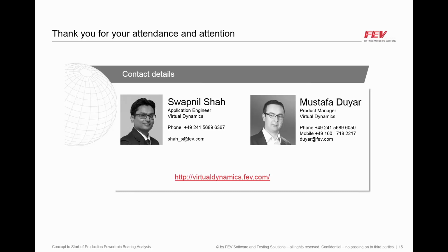So I'm guessing this question is for the chains. In a way, yes. You can still use flexible bodies in the chain. You can mesh the links and just import them, but it's not really been incorporated in the system. If you see the contact, you can only define the stiffness and the stiffness exponent. So you can still have the dynamics of the chain if you want, but it was not really included in the contact type, if that is exactly what you wanted to ask.